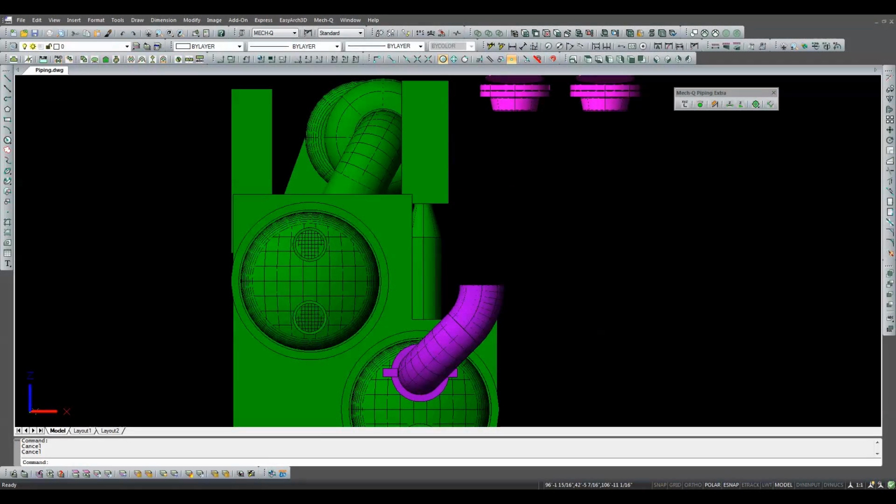I've switched to a front view of the chiller and removed all of the chill water supply and return pipe and fittings except these 2 elbows. We can see that the 45-degree elbow needs to be aligned with the associated valve. In this case, the slide axis falls along this 45-degree line composed of the end of the fitting and the focal point. The alignment plane is an imaginary plane that is made up of the center lines of the valves and the weld neck flanges.